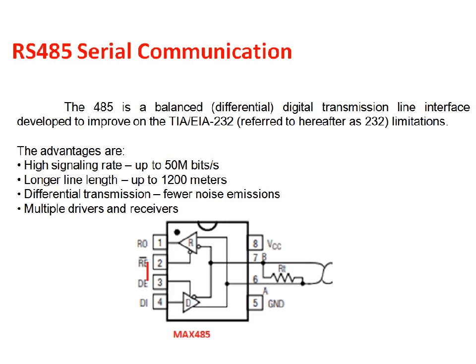Only at a time the sender can send or receive the data, because the differential lines A and B are commonly shared by the driver and receiver. Whenever data is to be sent, the driver is enabled, and whenever data is to be received, the receiver is enabled.